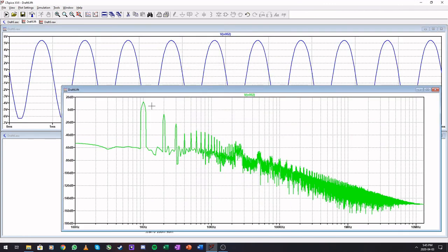Run it and look at that. These large harmonics that are being generated. And this is also due to the saturation at the bottom, and the top over here is a bit more, well, for lack of a better word, fat, not sinusoidal anymore. And you can see these effects in the FFT.